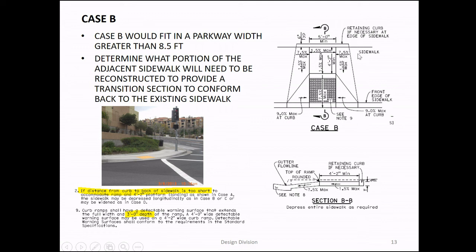Because when you don't have that strip, this guy is going to go from here to try to join here, but because the existing sidewalk could be anything. Yeah, even if the sidewalk is at 2%, you will need to transition from 1.5 to 2, so that will take care of it. But if the sidewalk is at 3%, that's another story.